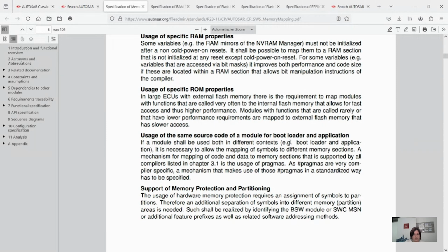Then you have, of course, also some bootloader functions, applications. You have the functionality, if you flash new code, to save the existing code, then flash the new code, and if everything worked fine, delete the old code. Flash the new code, and if everything worked fine, you can delete this backup you made. So these are things you need to do.